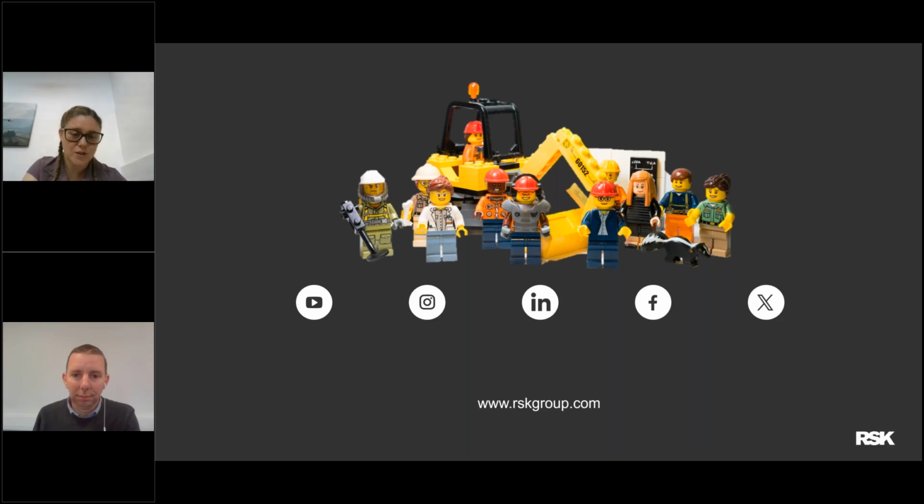It also depends on your geology. If you're looking at a site where it's tidal flats, you know instantly that that's going to be very soft material. So you're going to want to go deeper, because they're going to need deeper foundations to be able to support the loads. Whereas if you're in an area where you're straight onto limestone at a meter down, you're probably going to be able to do a shallow investigation. So it's very dependent on what they want to build and the geology that you've got on your site.